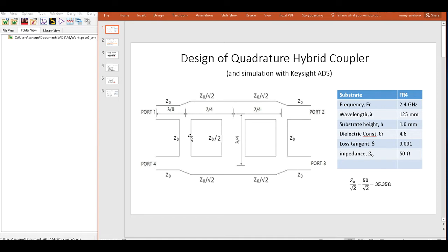Branch-line couplers are frequently used as crossovers. An ideal branch-line coupler theoretically has no coupling between the two ports through it. So our design here is a three-branch coupler, which we have as 1, 2, and 3, equivalent to a 3 dB 90 degree hybrid coupler.